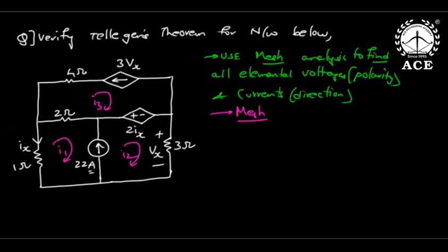Yes, everybody see here now. I just asked you to write mesh equations. Okay, I am writing the first mesh equation, starting from here: 1 into I1 plus 2 into I1 minus I3, super mesh, plus 2Ix plus 3I2 equal to 0. That is the first equation.